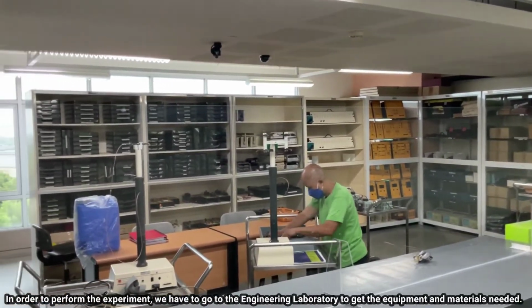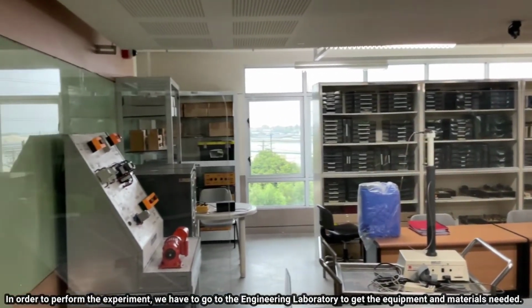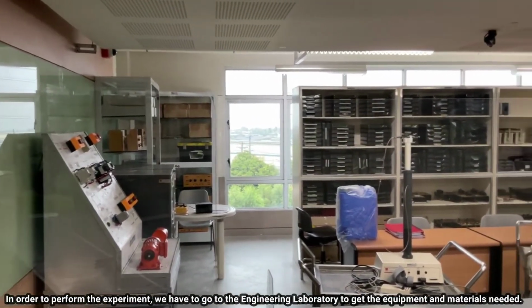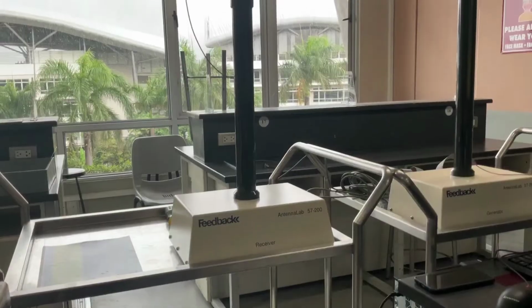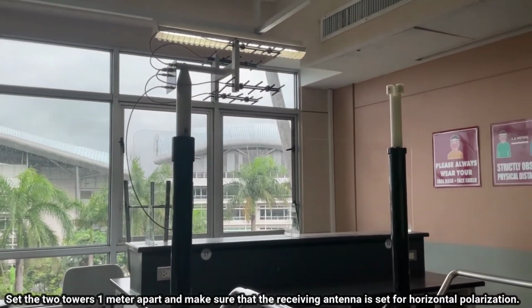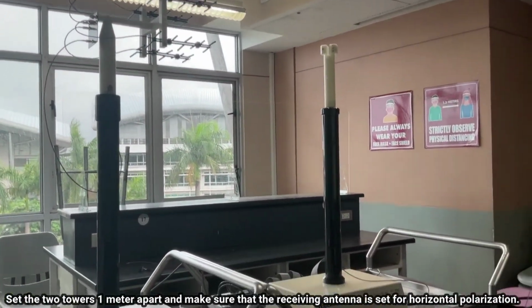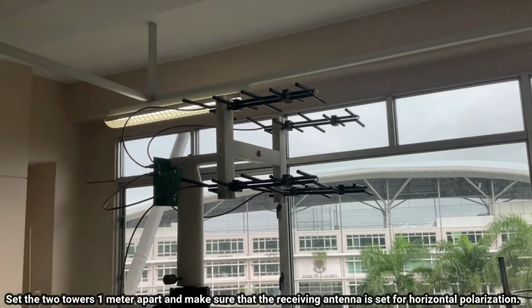In order to perform the experiment, we have to go to the engineering laboratory to get the equipment and materials needed. First step is to set the towers 1 meter apart and make sure that the receiving antenna is set for horizontal polarization.